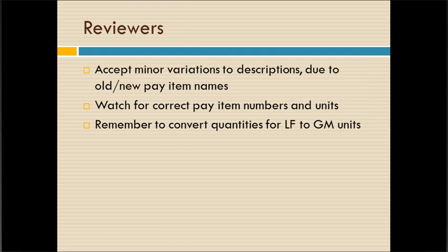The units, make sure if they have converted from a linear foot to a gross mile on the units, obviously those quantities must change. So you need to watch and make sure that they didn't just swap a pay item out, but those quantities were recalculated to the correct units. So again, we don't want to nitpick on all those descriptions, but we do want to make sure that the pay item numbers and the units there are correct.